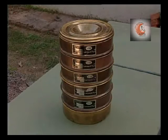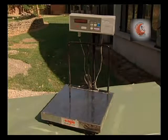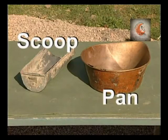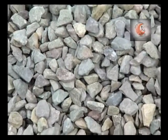In the present video program, we shall see the demonstration of sieve analysis of coarse aggregate for determining its size and gradation. The apparatus used to perform this experiment on sieve analysis include set of sieves, weighing balance, enamel tray, scoop and pan, and sample of aggregate under test.